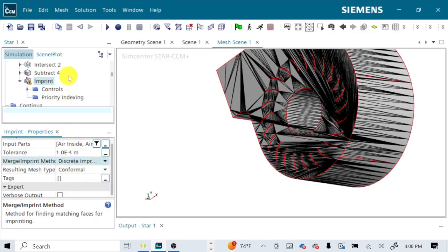If you were coming from NX, that would absolutely work just fine if you were coming directly from NX or something. But because we have tessellation error, these things aren't exact matches in a lot of places. They were still exact matches in an awful lot of places, as you saw, just not all of them. If you drop the tolerance way down, that would still potentially work, right?